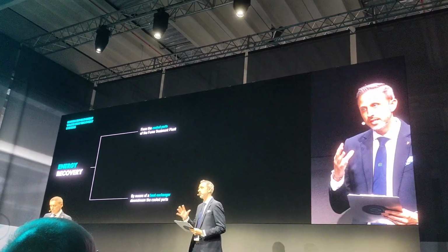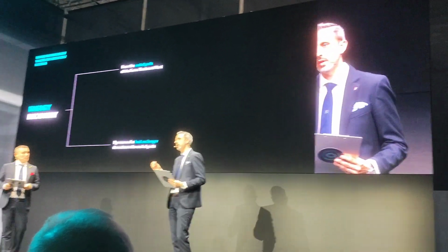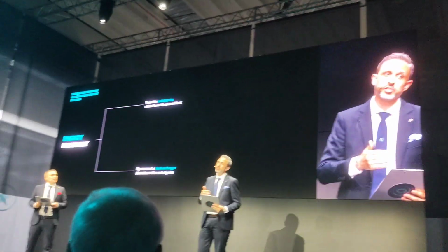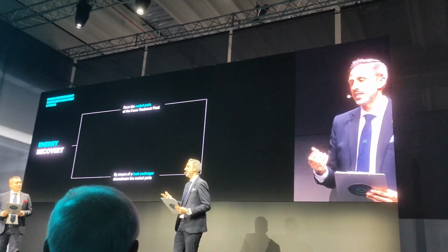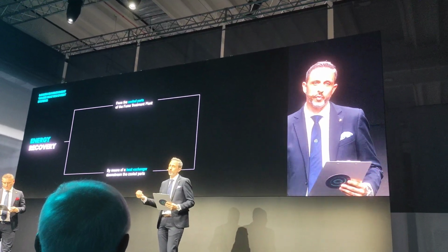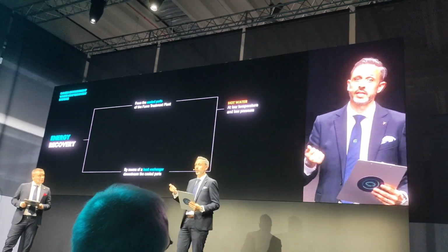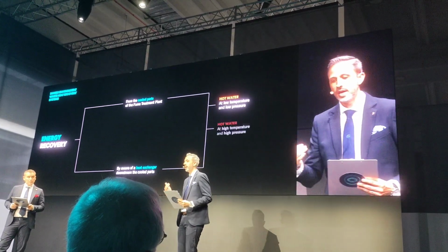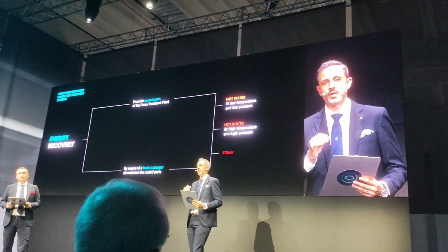But how can we recover this thermal energy? The waste heat that is contained in the primary fumes can be recovered in the fume treatment plant, in particular from two parts of the primary fumes line: the cooled parts and a heat exchanger that can be placed downstream the cooled parts. Basically, what happens is that the heat is transferred to a cooling media that at the end of the process inside the waste heat recovery systems can be transformed in hot water at low pressure and low temperature, typically 90 degrees, in hot water at high pressure and high temperature, typically 200 degrees, or saturated steam.